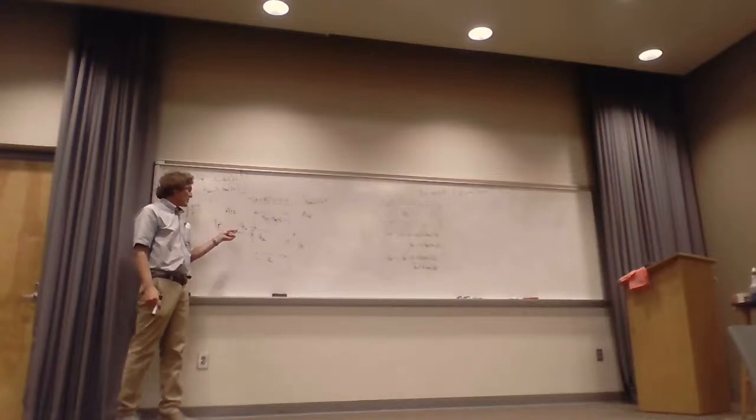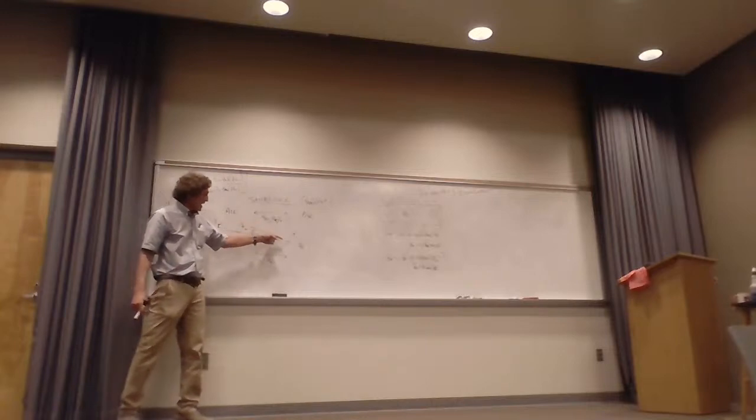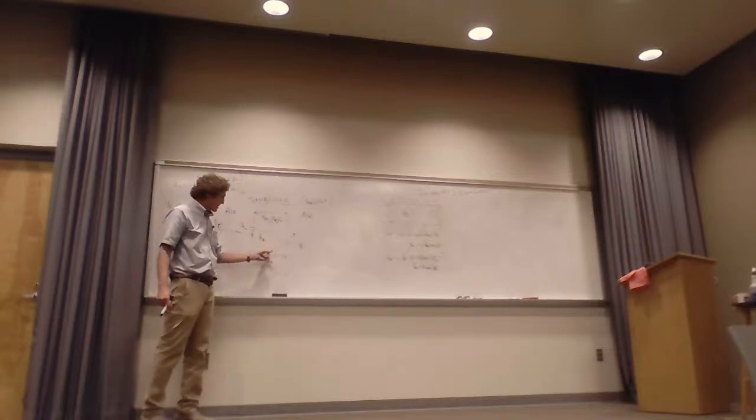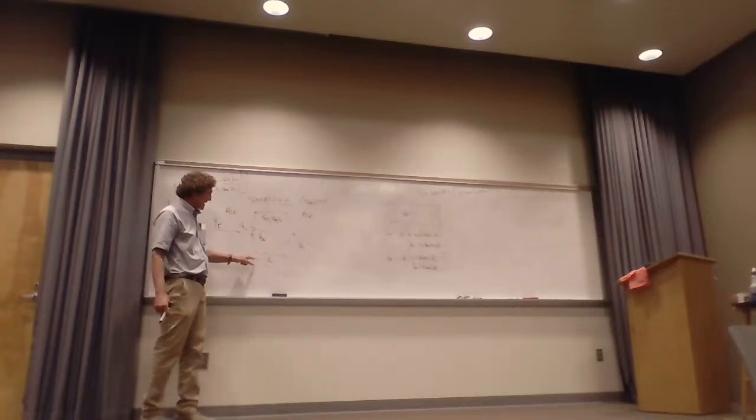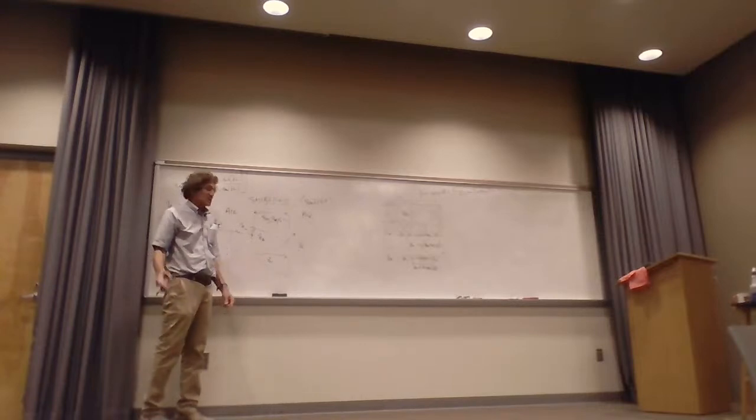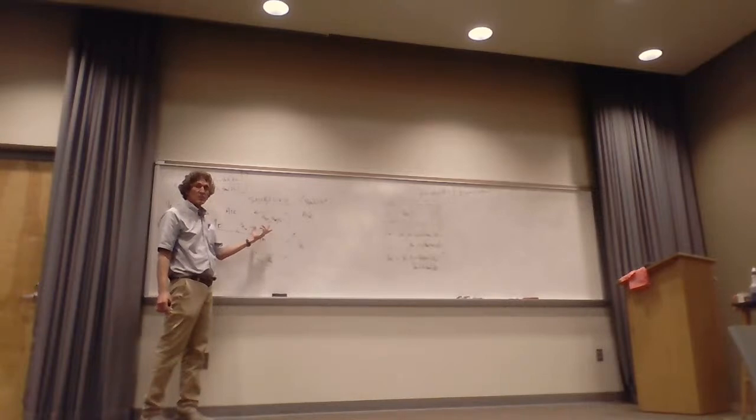Well, you would learn that the wave coming in here is going to come down, hit this and ricochet back, hit here, and every time it goes through, it loses a lot of its amplitude because it's conducting. When it hits here, only a fraction is reflected and it comes back this way. Basically, if you have a shield that's more than about a skin depth thick, you really don't worry about multiple reflection, because just think of this.